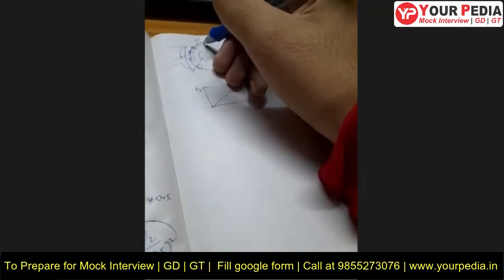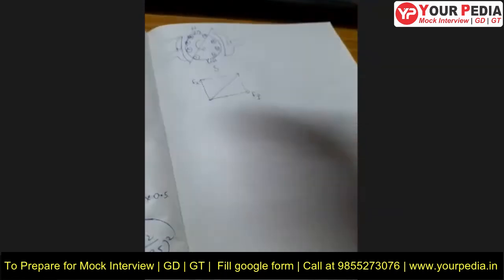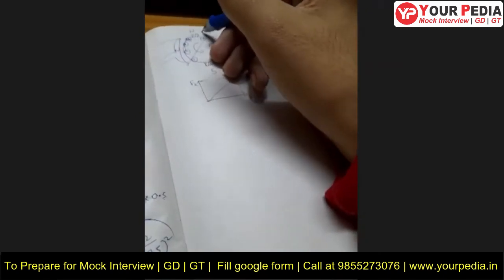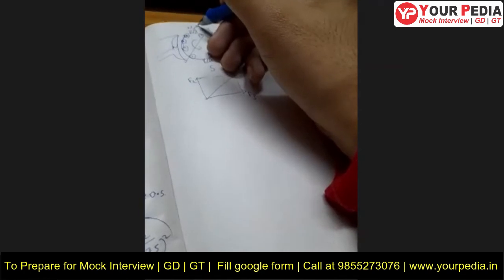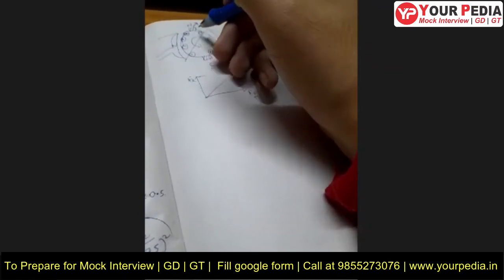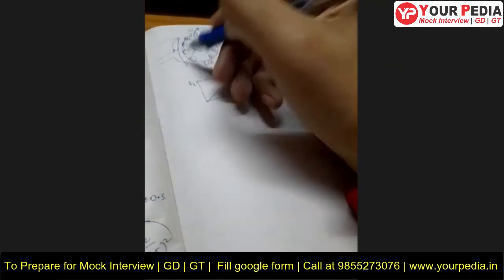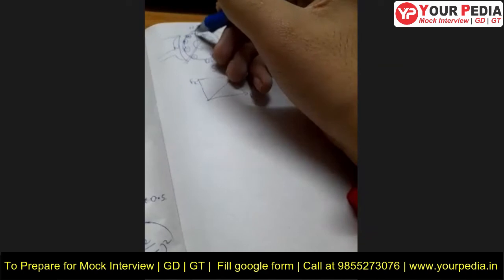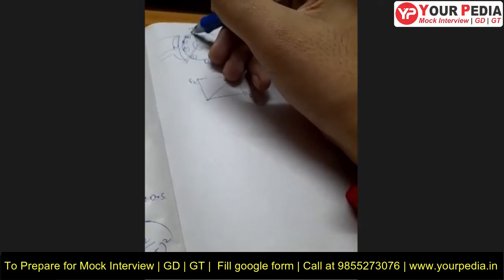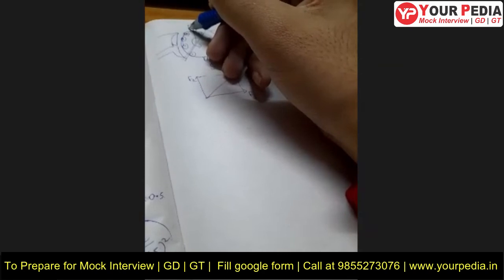If we don't change the commutator brushes, it is still not an interpolar axis anymore, because there's still a resultant flux flowing through this axis, due to which, where the brushes are kept, the windings will be shorted for the commutation process.